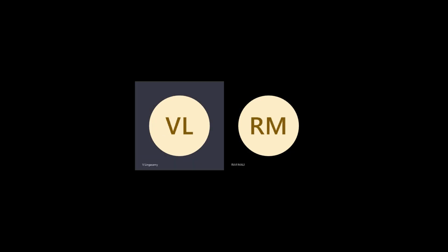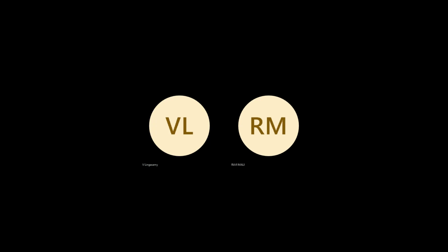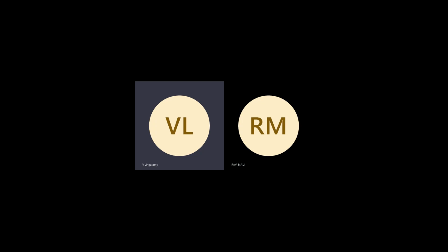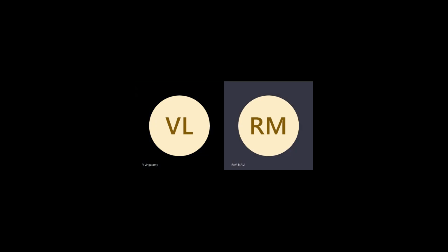See, in general we keep 0.5 lambda, or 0.7 lambda also you can keep. That again depends on the gain that you are expecting and how many elements you are planning for the array, all that stuff.